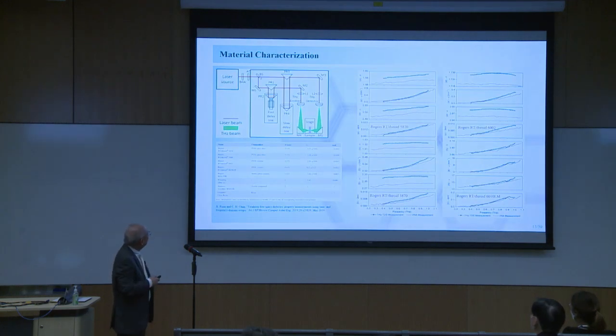We can also make use of the time domain spectrometer to do spectroscopy, and here we can measure different materials that we commonly use for our terahertz devices, and then we can extract the dielectric constant as well as the loss tangent of different materials.